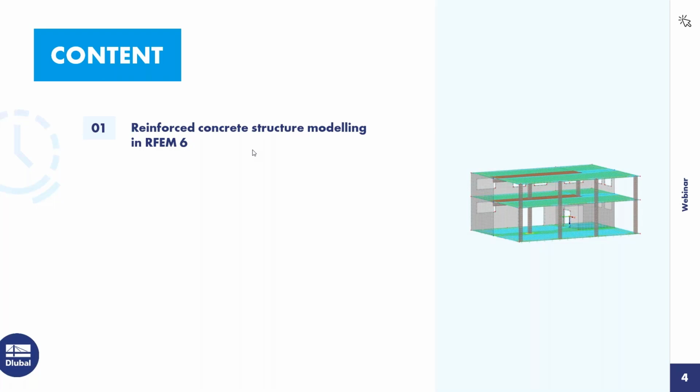So I will present today the modeling and the definition of some additional tools for the design of these reinforced concrete structures. I will especially take care about design of the slab over the ground floor. I will define some additional settings for the finite element mesh generation, take care about the singularities to avoid them and the joint of the column to the slab. We will go also into the design for the punching, which is especially on these nodes here where the columns are placed.